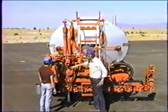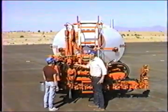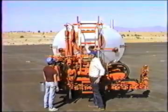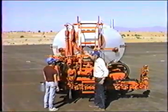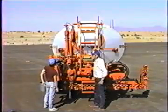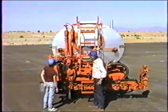So material that you've metered with the pump in order to put down the particular spread rate, rather than go on the ground, has gone back into the tank. So that would totally foul up all this very important metering that we get into on this. Again, the only thing we use that valve for is to circulate the tank. All other times it's closed.